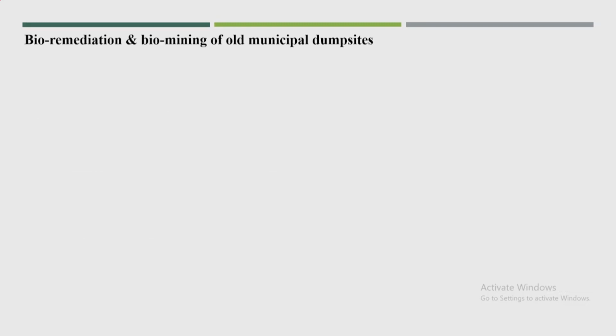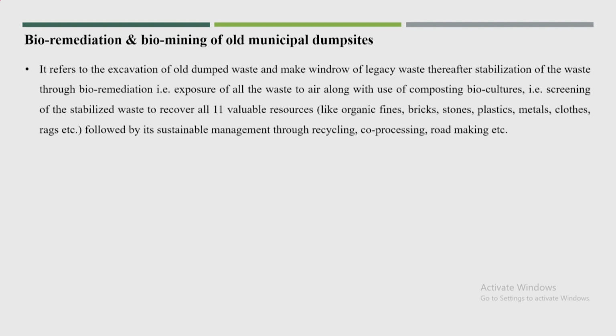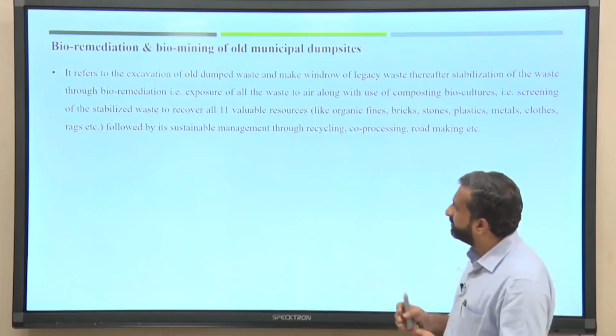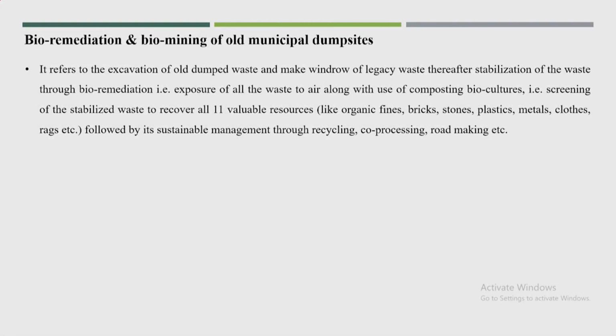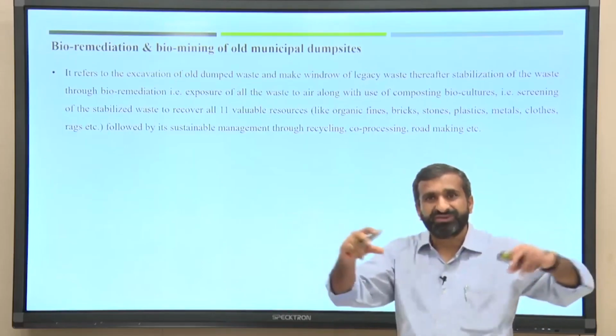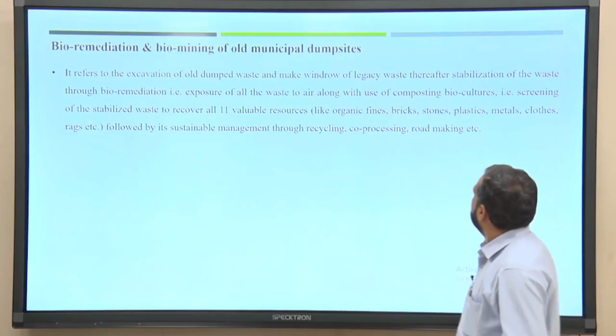So, what do we understand by bioremediation or biomining of old dump sites? It refers to the excavation of old dumped waste. When you say bioremediation or biomining, especially the word biomining, it refers to excavation of old dump site waste and making windrows of the legacy waste. Please remember the windrow from composting, when you talked about windrow composting. So, make a similar kind of windrow.